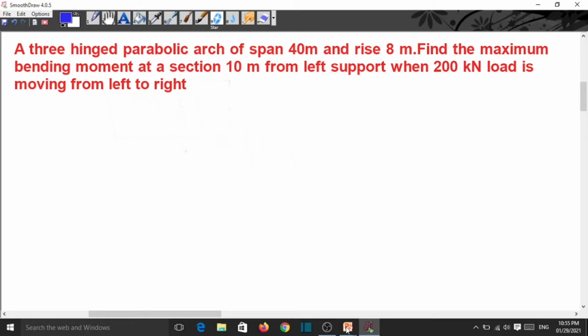Now this is a numerical: a three-hinged parabolic arch of span 40 meter and rise 8 meter. Find the maximum bending moment at a given section 10 meter from the left support when a 200 kN load is moving from left to right.